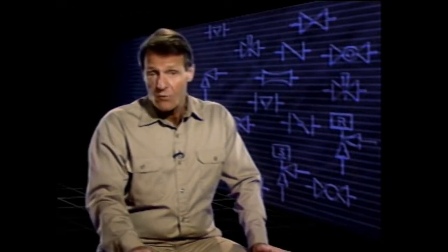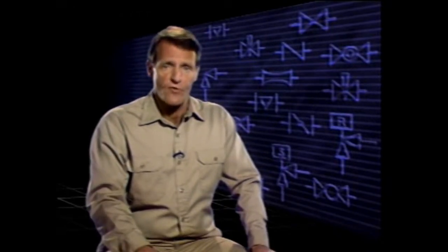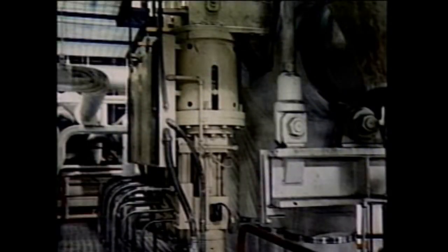Hydraulic actuators generally develop more force than similar-sized air-operated actuators. That's because some of the force exerted on an air-operated actuator is used up in compressing the air in the actuator. Liquids, on the other hand, aren't compressible for the most part, so more of the force exerted on the hydraulic fluid goes directly toward positioning the valve connected to the actuator. The power supplied by hydraulic actuators makes them very suitable for the operation of large valves.